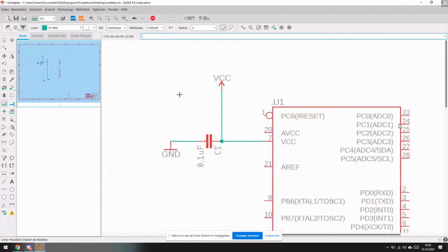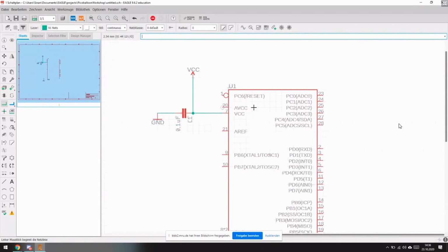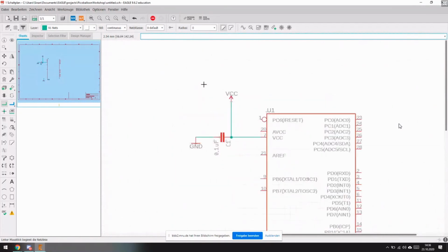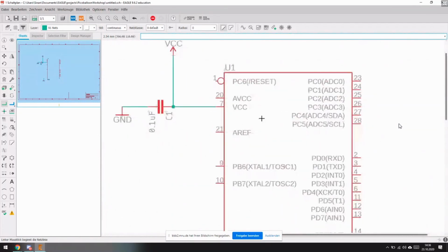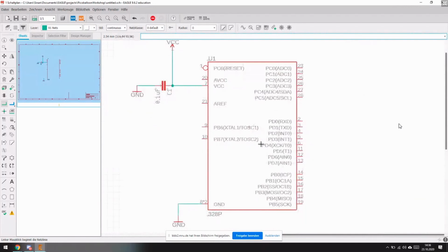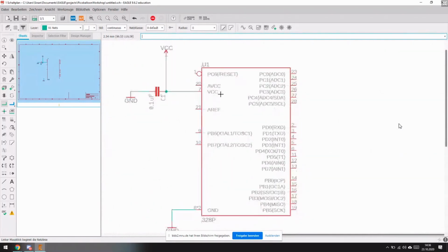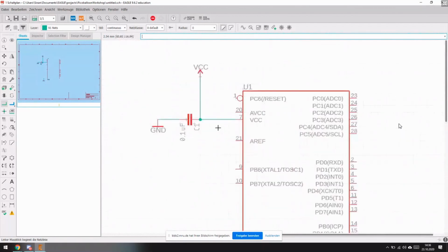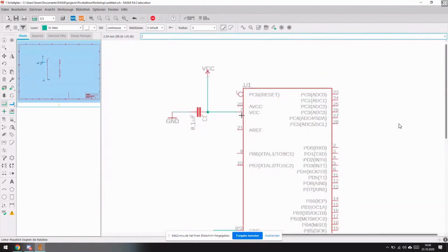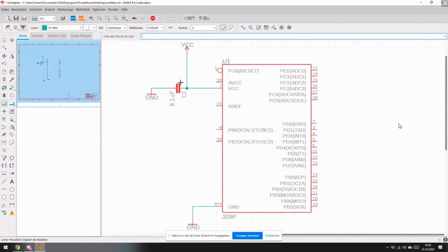Because of different phenomena, we could actually maybe kill our microprocessor or have dips, because sometimes the microprocessor needs much power for some clocks, and it's not always able to get the high current draw from the power supply if it's weak.